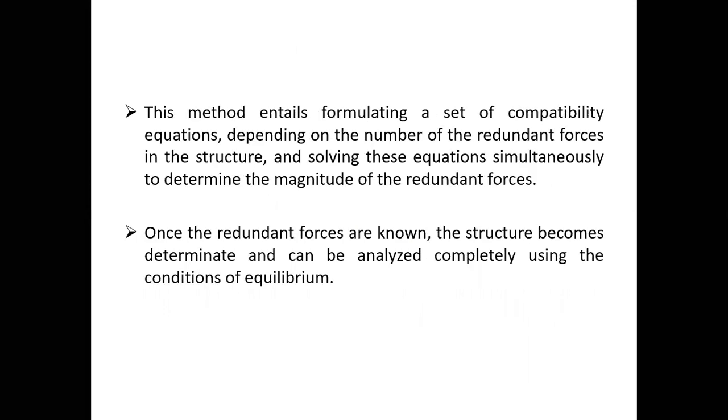Now, again, for the same flexibility method, this method entails formulating a set of compatibility equations depending upon the number of redundant forces. Once the redundant forces are known, the structure becomes determinate, as I told you, and can then be analyzed completely using the conditions of equilibrium. The basic approach in this method is, first of all, we modify the support conditions and convert an indeterminate structure to a determinate structure, and then we analyze this transformed determinate structure using the equilibrium conditions.